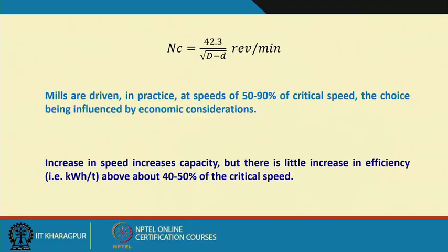So, in both the cases you have to make a compromise on what speed and how much money or how much energy I should be utilizing, and these are the difficult decisions, the challenges of mineral processing operators or mineral processing engineers: what should be my optimum mill charge, what should be my optimum mill RPM or the optimum input energy to be utilized.